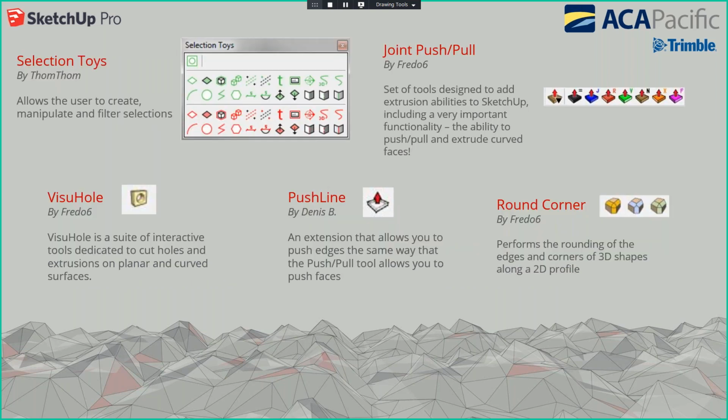Okay, so these are the 5 extensions that I think will be very useful in your own workflow. Let me give you a brief overview of them before I go into the demonstration. The first one is known as Selection Toys, developed by TomTom. This allows the user to create, manipulate, and filter selections. This is a foundation tool which I feel is very important, because it allows you to filter the items in your model based on whether it is a group, a component, arcs, circles, or different faces. We have this functionality to easily filter out the items that you want to select.